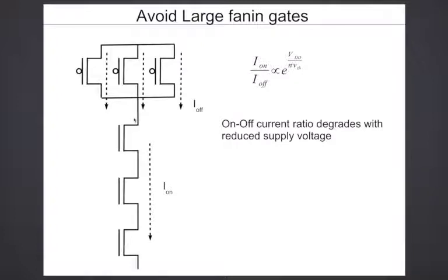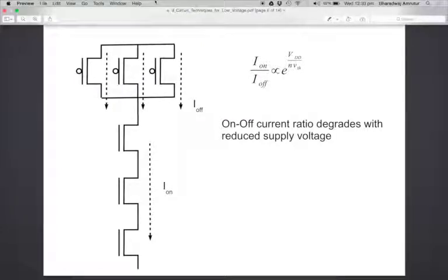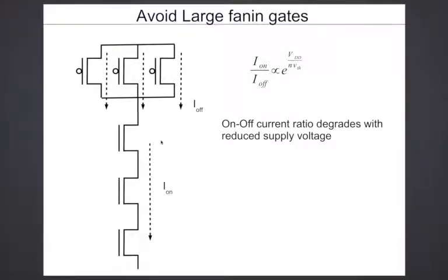So if you put a diode connected NMOS, then the time required for pull-up will degrade very rapidly, because as the circuit is pulling up, the gate source voltage will start reducing and the current will start dying exponentially, right? So you will have a problem with the pull-up speed. If you put a PMOS diode, what you have really done is effectively reduced the supply voltage and put a series resistance again, right? So that does help the imbalance issue, but it will also affect your pull-up speed.